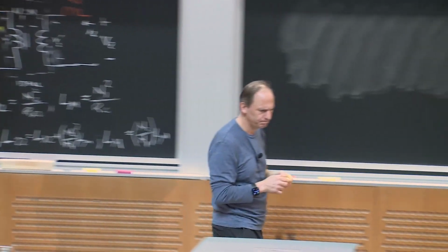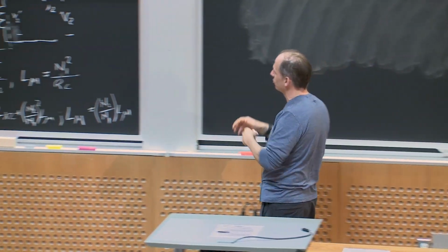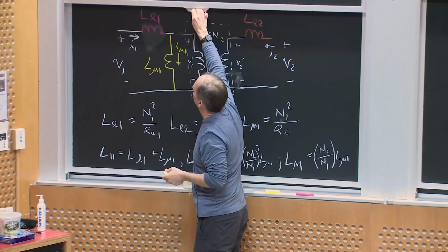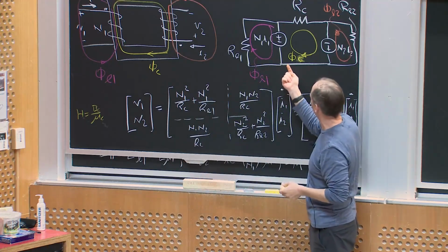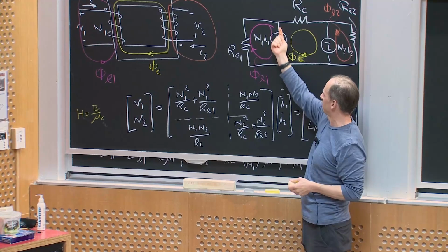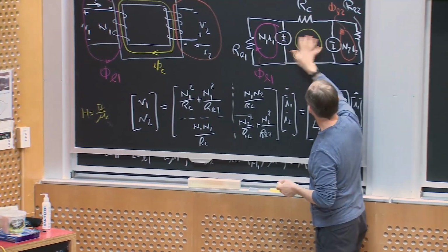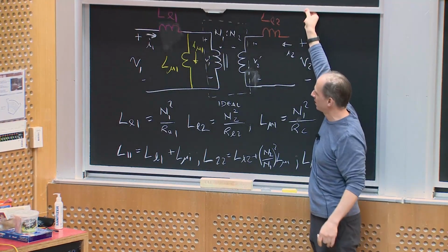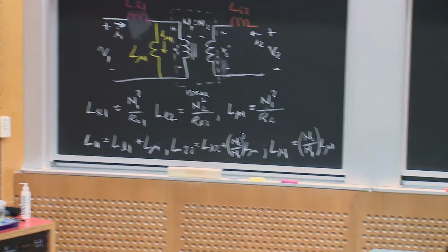The last thing I'll note is that you ought to be careful in your own analysis: the flux of interest for the flux linkage, to relate to voltage on the electrical side, is the flux coming out of the positive terminal of the MMF source. So you have to pay attention to your signs, especially when you have multiple windings, and that comes back to representing Lenz's law. Let me stop there and ask if there are any questions.